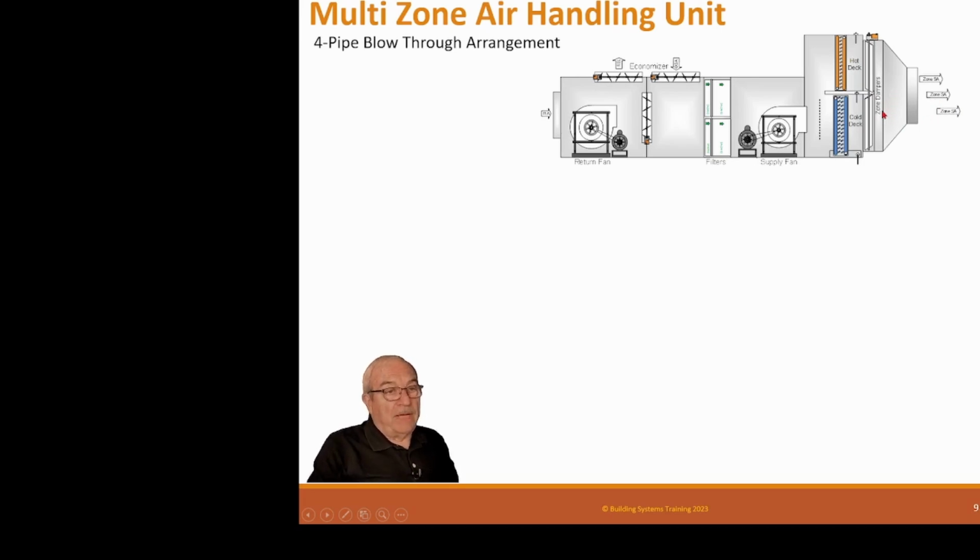Now, back when I was a designer a long time ago, you get a job that needs 11 zones. Boy, trying to get 11 ducts off this unit was miserable, because these may be 6 or 7 feet tall, and you may have a 4-inch wide duct. So it's a really wide duct, because what happens on this duct is it has a cooling damper and a heating damper on the same shaft.